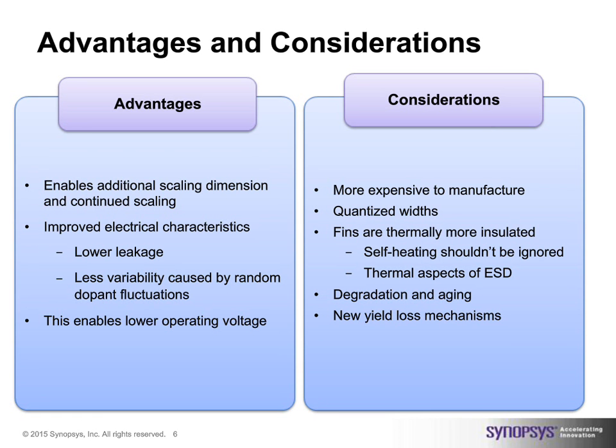Also, there is an issue of heat. This self-heating of the fins also has complications, as we will see later on. The fact that they are not entrenched in the body itself, but sit there in a three-dimensional way, with some self-heating possibilities, will give us certain disadvantages as well. It will be shown in degradation, in aging, and of course, with new mechanisms being built, we'll see losses in yield initially, so we need to contain that also with solutions that take care of yield, as we will see later on in terms of repair and so on.